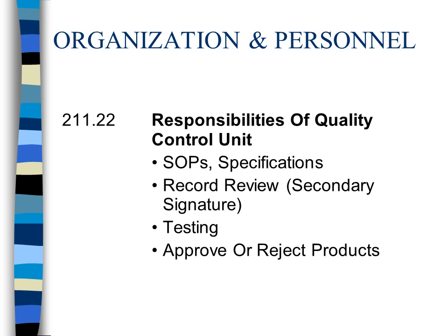And not blatantly, but he did skip a step. For example, you may have skipped the evacuation step. It is the responsibility of the QCU member to reject that rack, make the processor blow the cylinders down, evacuate them, and refill them.